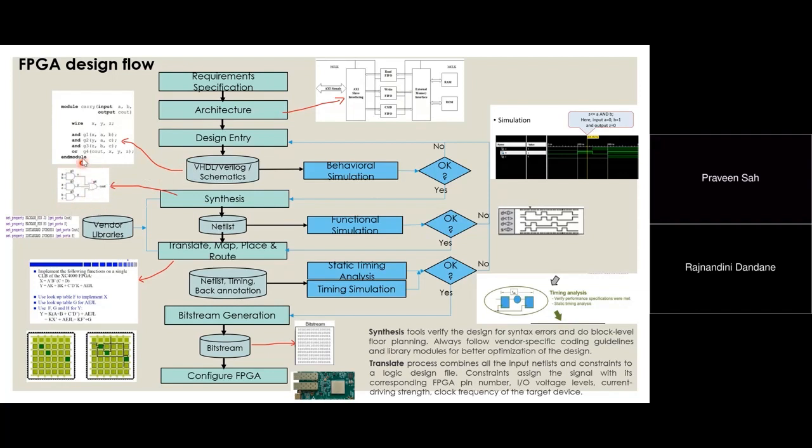You see, whatever it was there, ABC, it is X. AC output was Y here. BC output was Z. It is here, and now you are using an OR. So it is nothing but this G4. So whatever you have written, synthesis is nothing but it translates this logic into the gate level netlist.